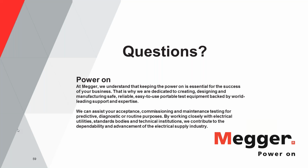Okay. Next question. Could you please go over the short time pickup? Not sure where you get the STPU value. Also, if the short time is set to 0, is it the same as the instantaneous? So trip units have a long time pickup, they have a short time pickup, they have instantaneous pickup. The short time pickup can be set as various options. It can be selected as a multiple of the long time pickup or of the rating of the current plug. So you can select any of the settings that's provided on the trip unit. You don't have to stick to a particular value.